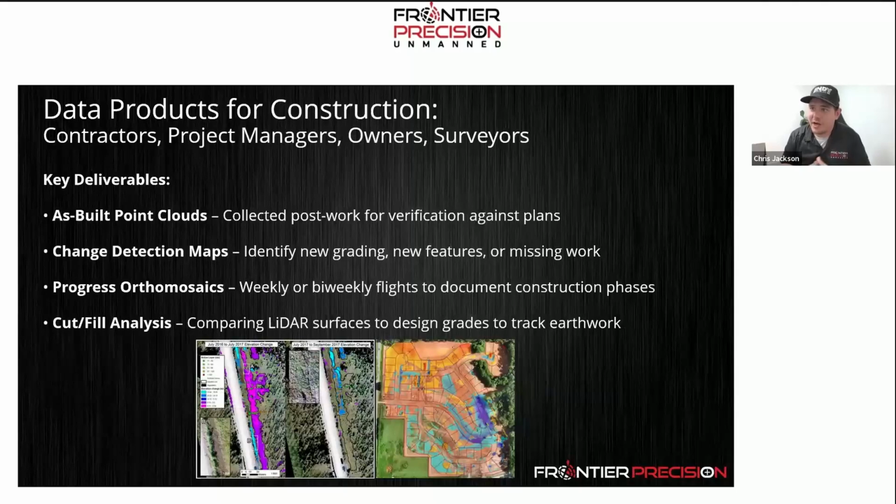And for construction, so contractors, project managers, owners, surveyors, some of the things that they're looking for commonly are as-built point clouds. Before something gets built, a pre-build survey is performed. You also want to do that after whatever is built, and you want to be able to compare how close those things line up. Change detection maps can also be used as an as-built, to see what's changed from one point in time to another. Same thing with progress orthomosaics, and then cut and fill analysis. Again, if you're doing any earthwork, it shows you where your low points are, where you need to put material or where you need to take material out to get a flat surface.